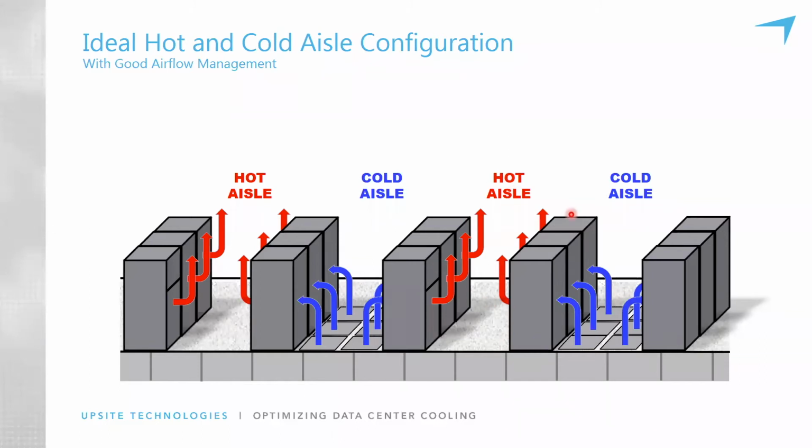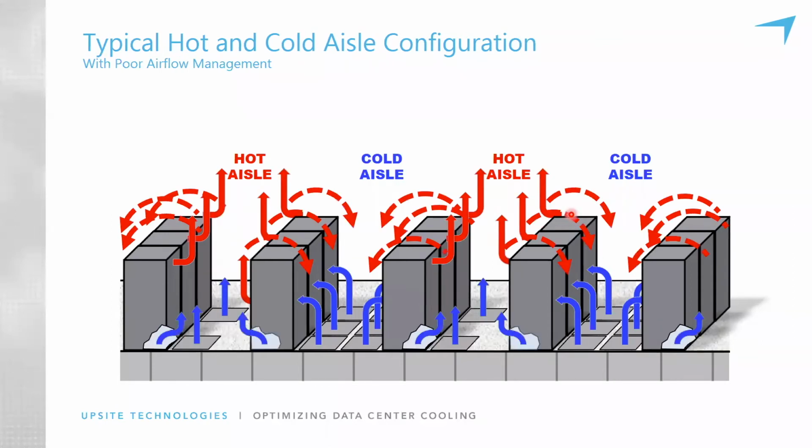However, airflow management is invisible. Air moves and we can't see it. So unfortunately, this is the reality of what's going on in many computer rooms. And just a few things to point out. We have air coming out of unsealed cable openings underneath the cabinets. There are some misplaced perforated supply tiles in a hot aisle or maybe out in an open space in the room.